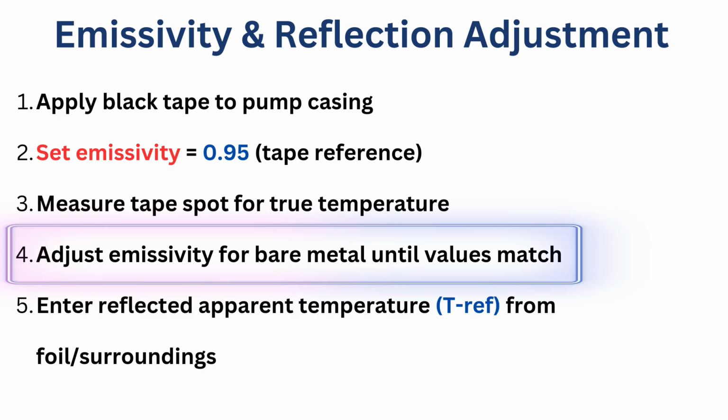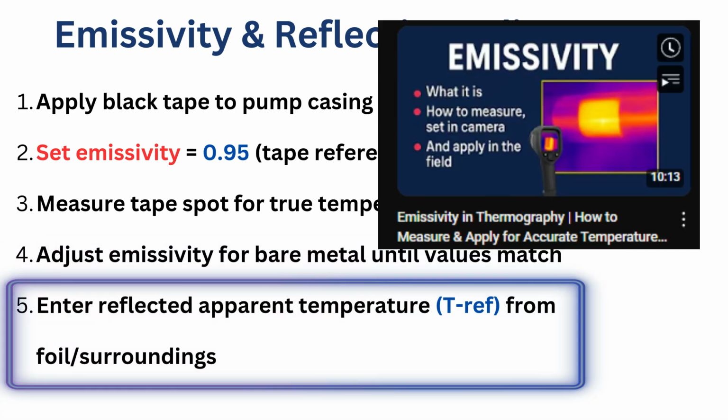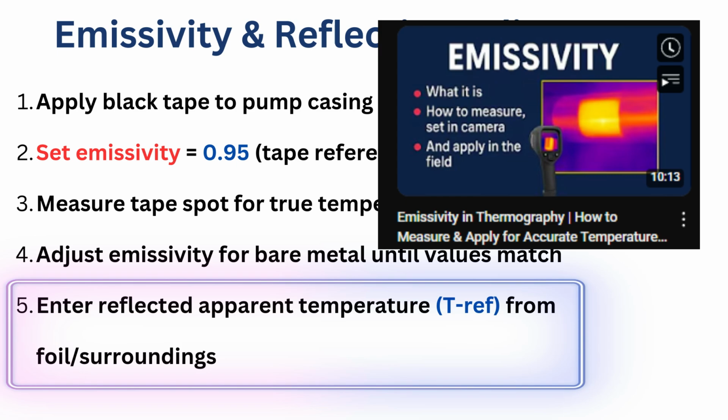And please make sure that you always take care of the reflected apparent temperature, which you can measure by using the foil. If you want more detail on this, please refer to our last 7 to 8 videos that we made on thermography.